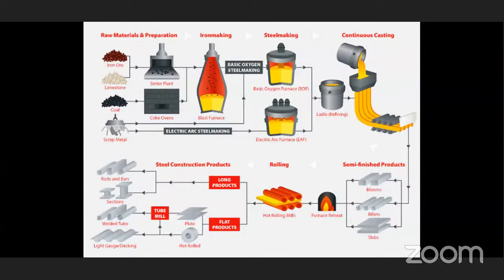The type of process that is going to be operated depends only on the raw materials. If pig iron is low in sulfur and phosphorus, the acid process is used, and the slag is required to retain only the silica and manganese oxide.